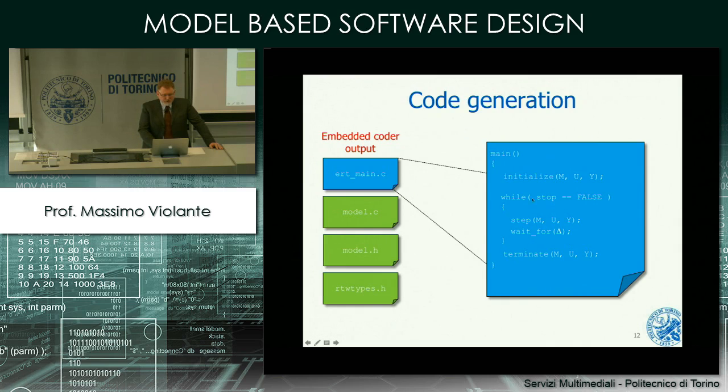As you can see, the pseudocode that I placed here reminds us of the way the Simulink solver works. We have an infinite loop. In each iteration of the loop, we evaluate the model, we update the state, we update delta, and we repeat. And this is what is happening. We have a loop that goes ahead until we are at the stop time of the simulation.